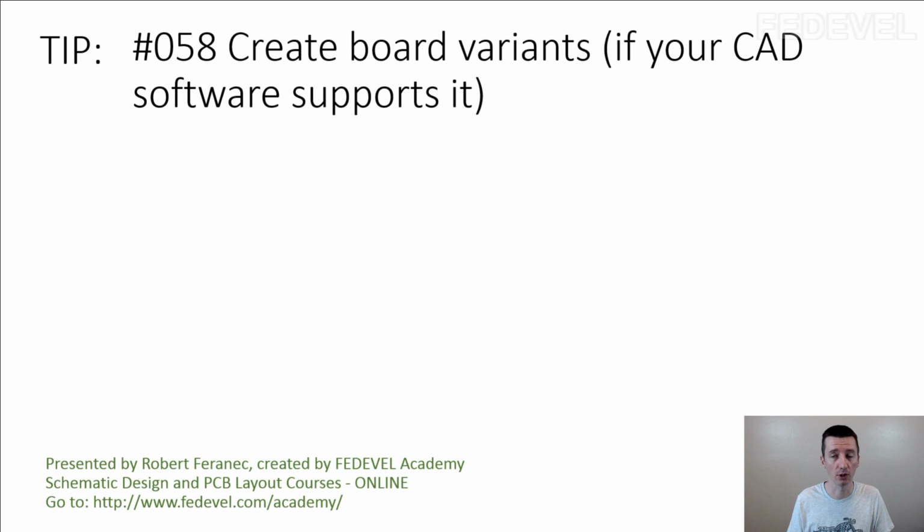And then when you are generating the manufacturing documentation, if you don't have variant support implemented properly, you need to manually go through the old BOMs and compare them with the new BOMs and adjust the lines, delete the lines manually. You can make a mistake and it is time consuming. It is much more difficult than just pressing buttons, because that's what you do. If you use the variants correctly, you just press a button, everything is generated correctly.